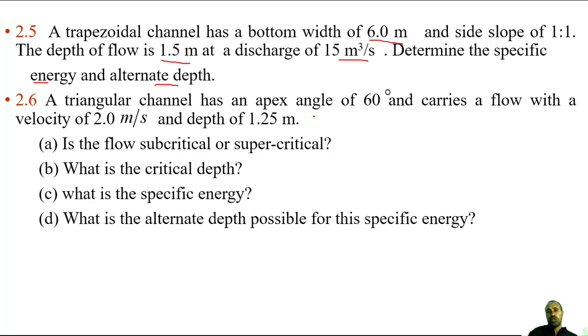This is also a triangular channel with apex angle of 60 degree and carries a flow of this one. And the depth of this, is the flow subcritical or supercritical? We can check with the Froude number, which is V over square root of G times D. D is the hydraulic depth for triangular channel, area over top width. Then what is the critical depth, etc. You can try. So this is just as assignment you can try.